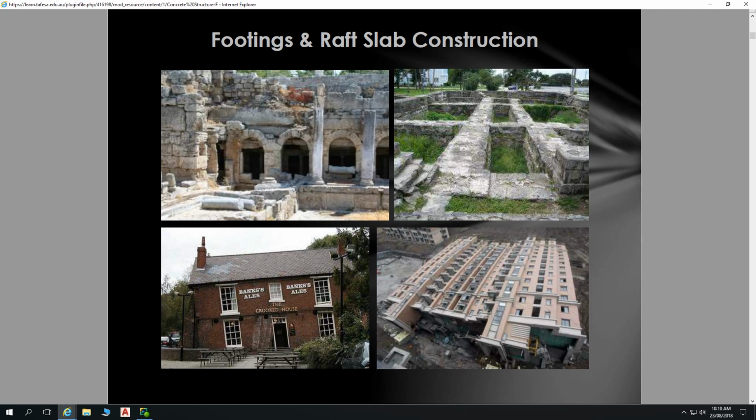This piece, that's a reinforcing cage, a miniature one mocked up to show what we typically deal with. The size we normally deal with is maybe 600 deep, 300 wide. Take off 40 mil for coverage. We've got some deformed bars, and those deformed bars bond well with the concrete, and then we have ligatures holding those bars together. Those ligatures space those bars at the correct spacing, and then we've got tie wire tying the ligatures to the bars to make a reinforcing cage to ensure those bars are in the right place.